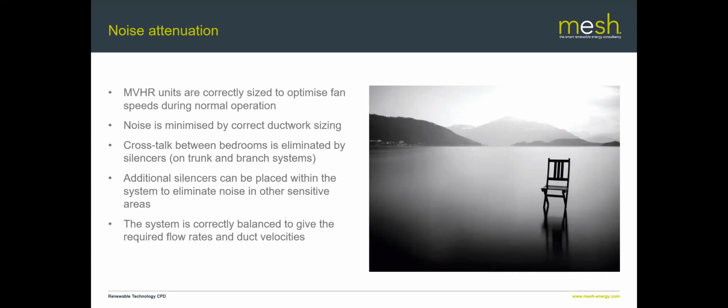And the final thing is the commissioning. Obviously, it's all very well designing a beautiful system, but if it's poorly commissioned and you don't have the airflow rates correct, then you might end up with unintended or unexpected noise. So that's all about good commissioning. But that also ties back to the design, because if you don't get the design right in the first place, it's going to be impossible to commission correctly. So it's important to get the design right.